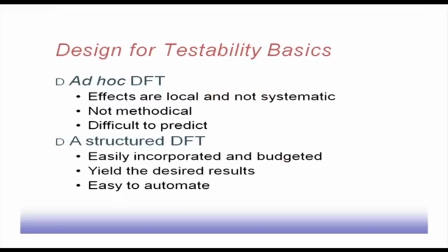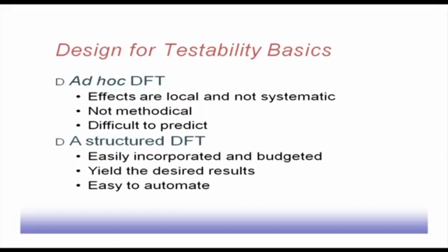On the other hand, with structured DFT, along with the design itself, we incorporate the testability hardware, and it is budgeted at that point. It is the extra for extra testability. I will need this much extra logic gates, this many flip flops, or this much area. That is put into the budget itself. So the test engineer can be sure that I will have this much extra that I can incorporate into the design to yield the desired result.